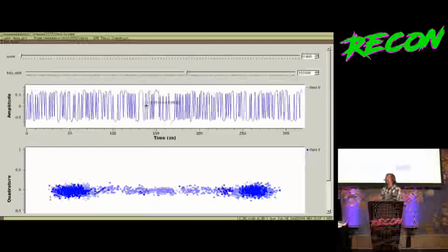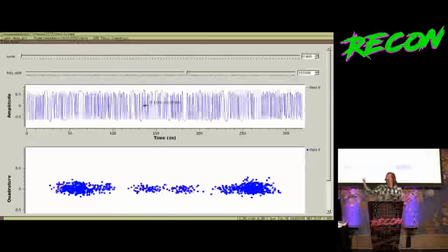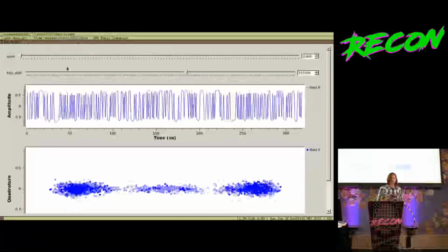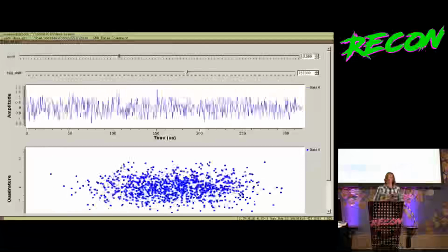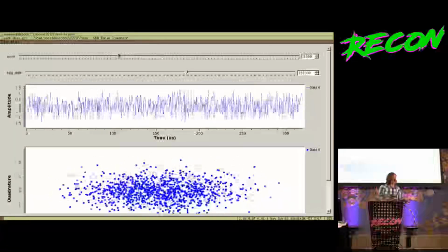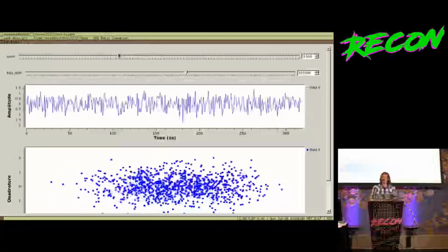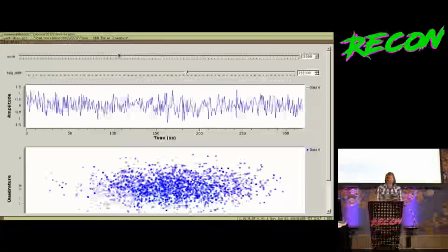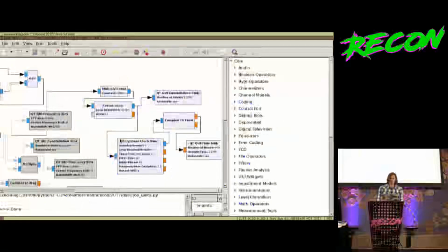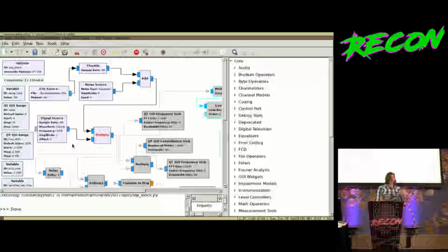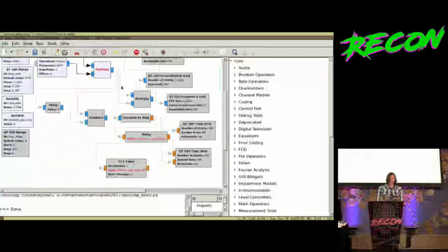But what if you were trying to pick up a signal that was being transmitted from the satellite, not the signal that was being transmitted by a handheld device? I would have a much worse signal to noise ratio, and if you start adding noise to this system, this technique totally breaks down. You can't just do a traditional BPSK demod to recover the chip sequence if you have a terrible signal to noise ratio. So I've been looking at ways to continue this process of reverse engineering and actually recover the chip sequence, even in the face of a lot of noise and interference.